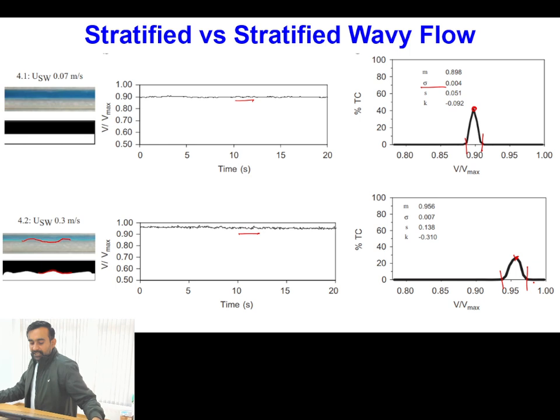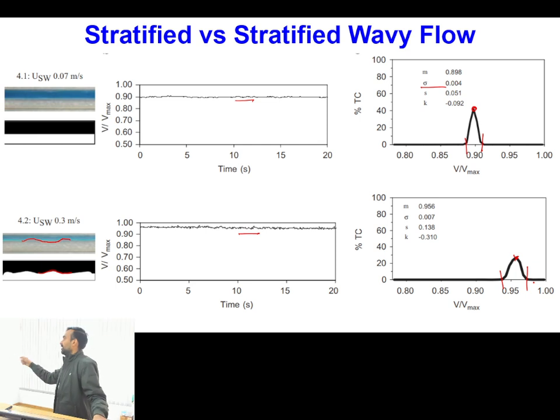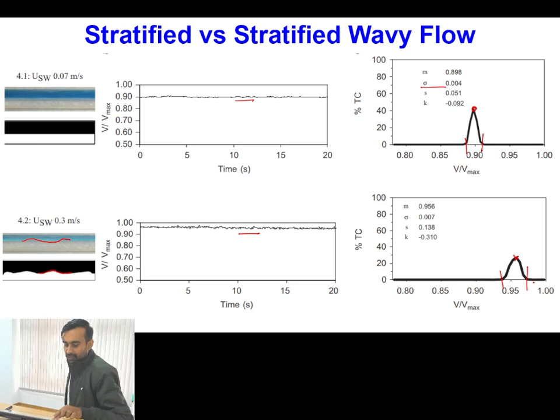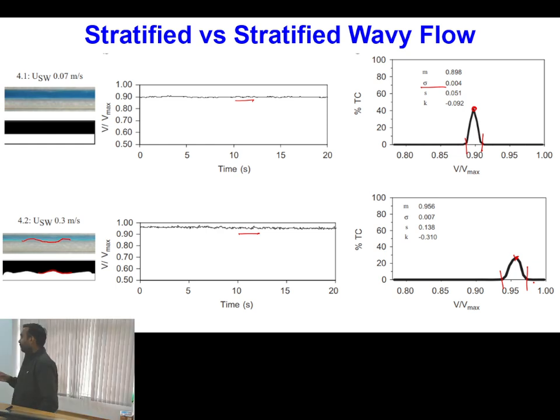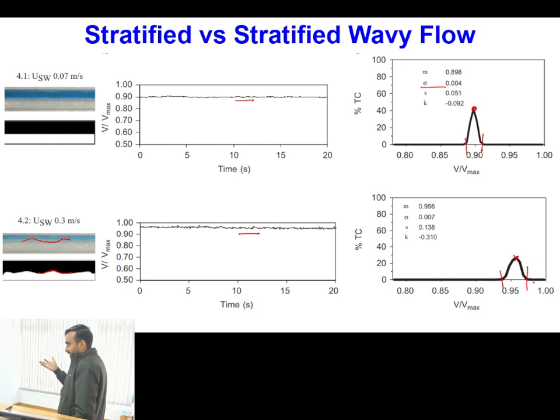So basically, when you are calibrating this device, you need to perform some analysis of the data, and you need to identify some characteristic features of the data which are unique to a particular type of flow pattern. Whether you operate in the smooth flow regime at a velocity of 0.07 meter per second or a velocity of 1.5 meter per second, if the identified characteristic of the signal is unique, then you will always be able to describe the behavior of the flow pattern. Is this point clear?